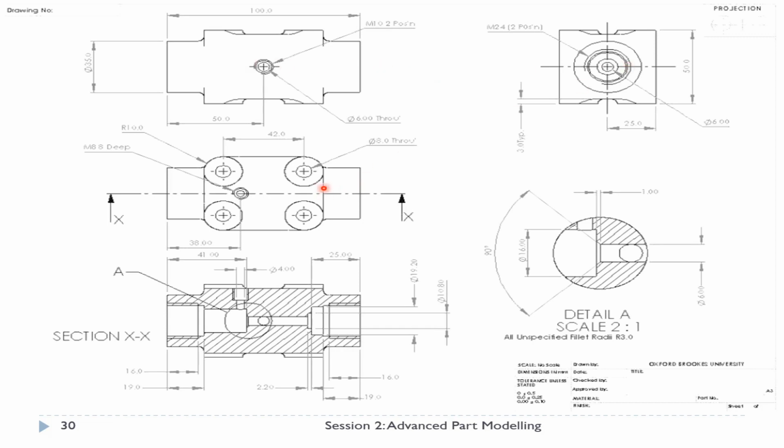What we see here are three main views of your part. Here is what we see from the front. Then this view is what we see from the top. If you look at the top of this part, that's effectively what you would be seeing. And if you look from the left side of this part, this is effectively what you would be seeing.